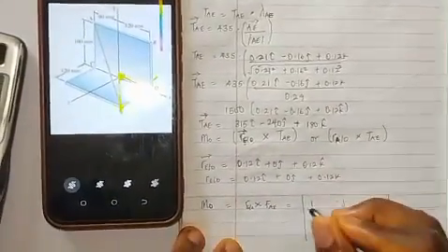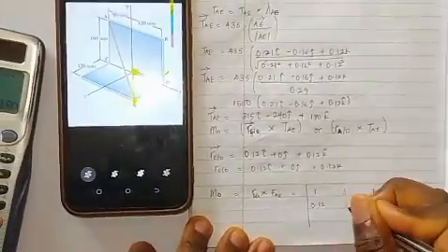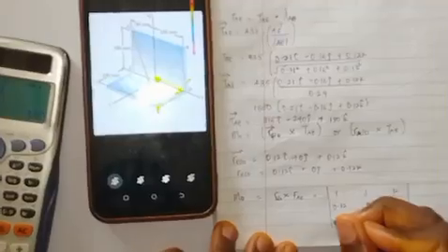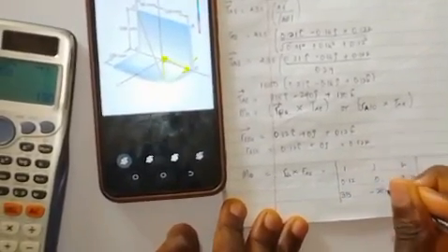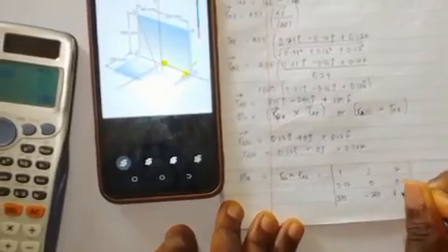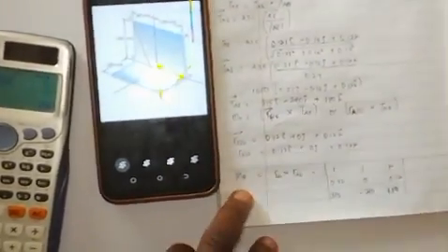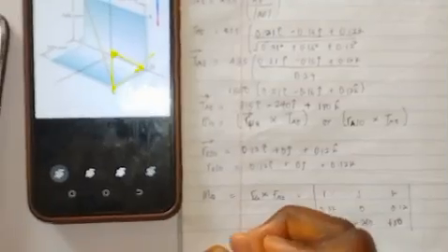So we will be having 0.12, 0, 0.12, then our tension, which is 315, minus 240, plus, sorry, this is 180. So the moment about point O will be the determinant of this particular matrix. So that means we can say MO.